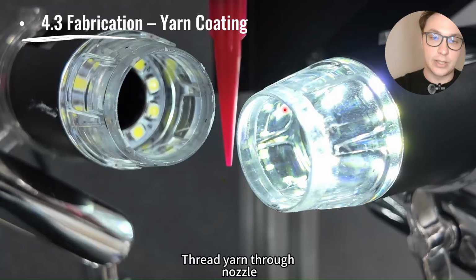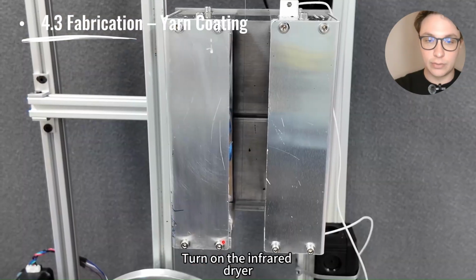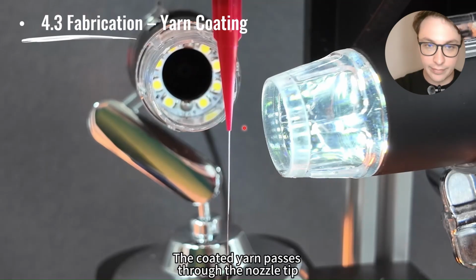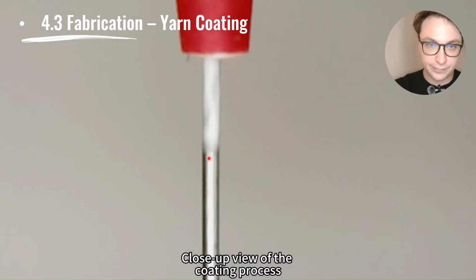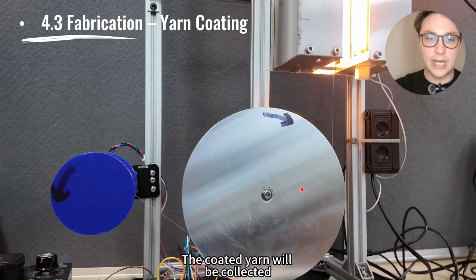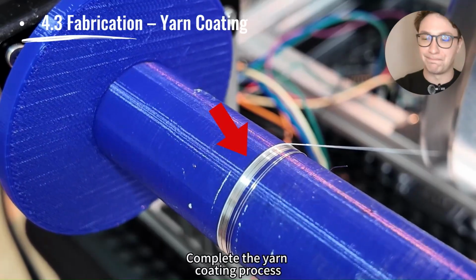So the thread yarn is passing through the nozzle here. We apply conductive ink, which is collected also in the syringe. This is the heater for the annealing after the coating. And as you can see here, we have the coated yarn. This is a magnification. There you go. And this is basically it. So the yarn passes through the heating system and is collected with this rotary system. That's it. Very simple.